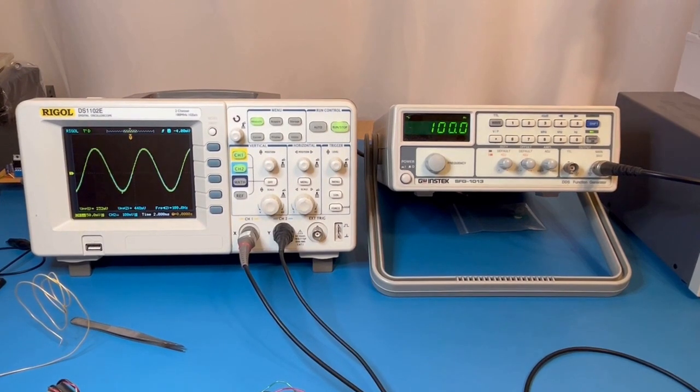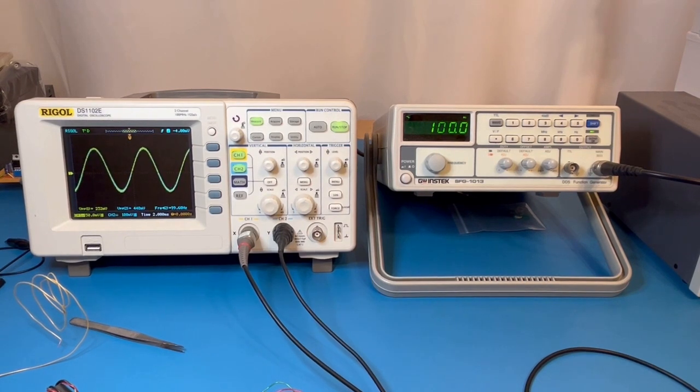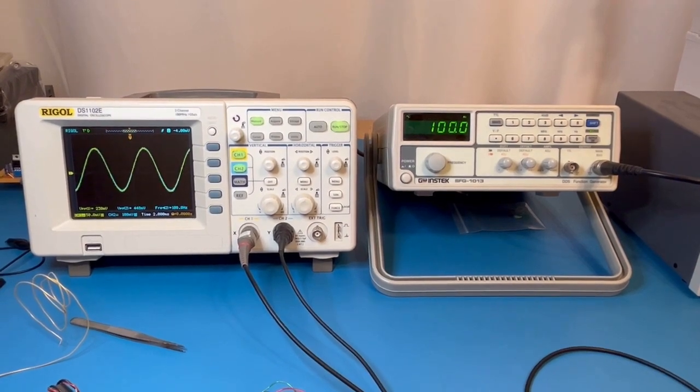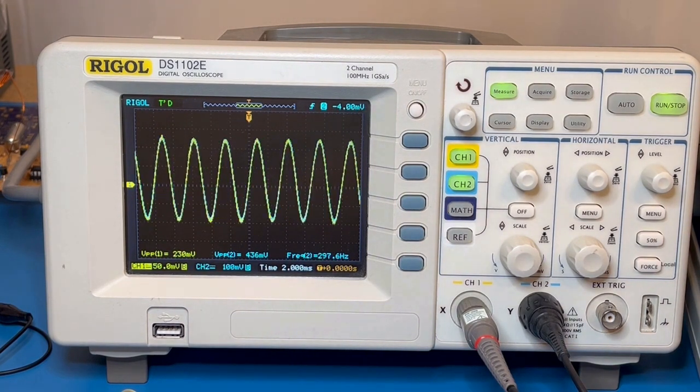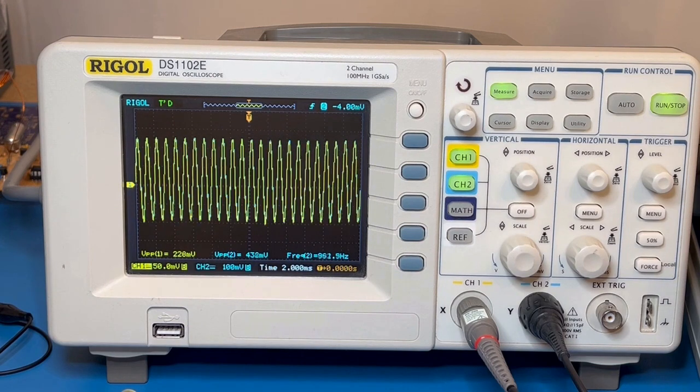So now we're going to take a look at what happens when we increase the frequency at low amplitude. Here we're at our 100 Hz with the oscilloscope set up so that the scaling factors cancel out the factor of 2 gain from the circuit. So this is fairly low amplitude. The output is less than half a volt peak to peak. 100 Hz, increasing it to 1 kilohertz,